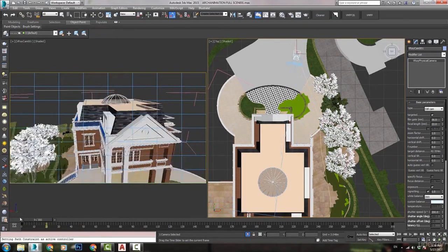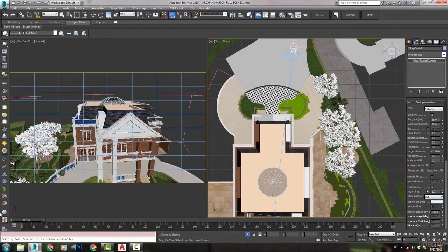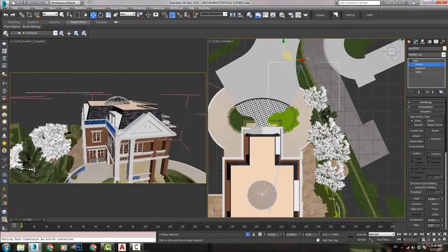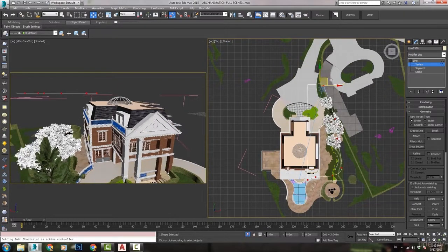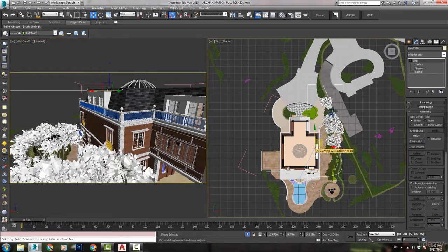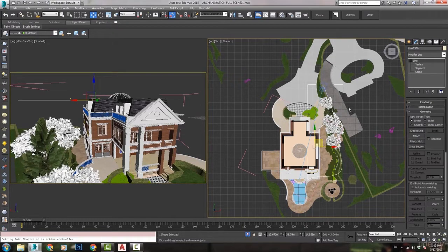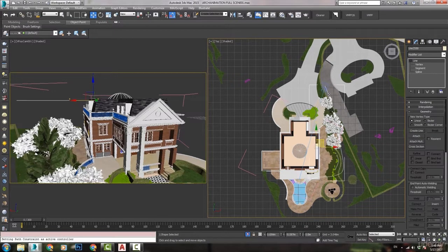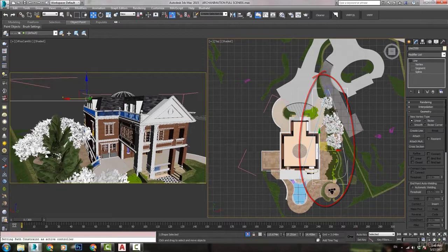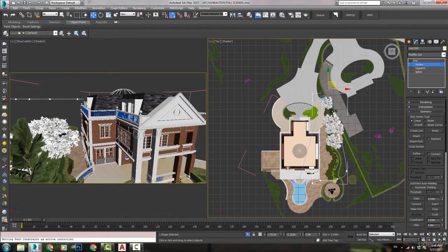Okay, what if I want to adjust the position of the camera at the first frame? Well, now I will need to move the vertices of the line itself. Now I continue adjusting the position of the line and vertices to get a decent first shot for my camera. Do not try to move the camera itself. It's a mistake. Only move the line and vertices. Now my control of position will be by moving the line as a whole, like this, or by moving the vertex like that.